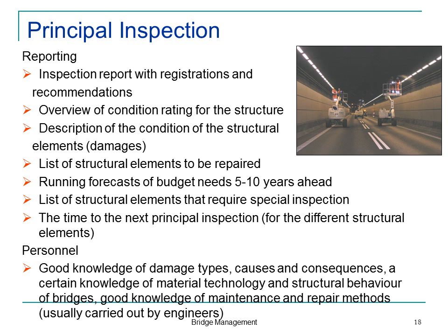The larger the crack width, the faster will salt and water penetrate, and the faster will corrosion go. They wanted photographs of all of them, measurements of all of them, and registration with the GPS. I think those who asked for it were people who had never been in the field.